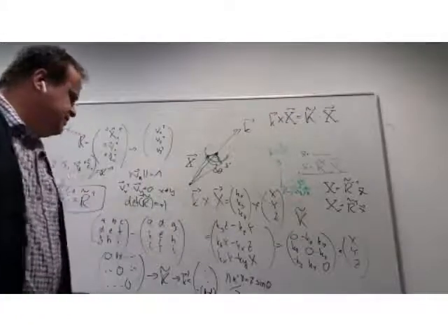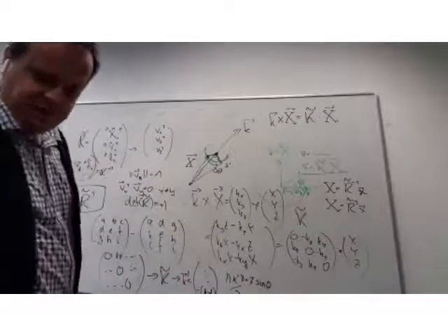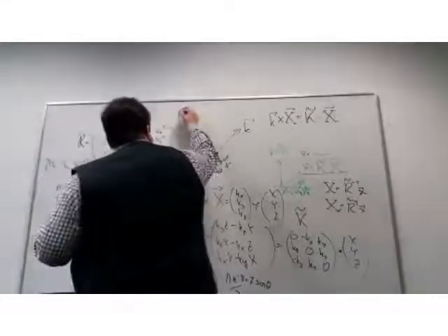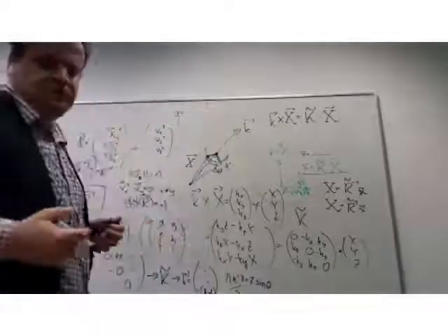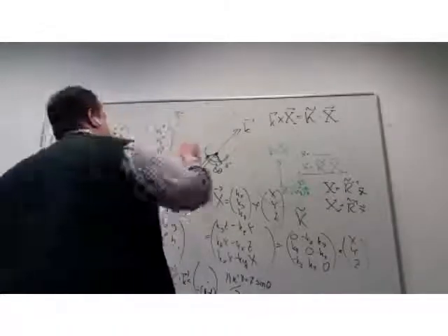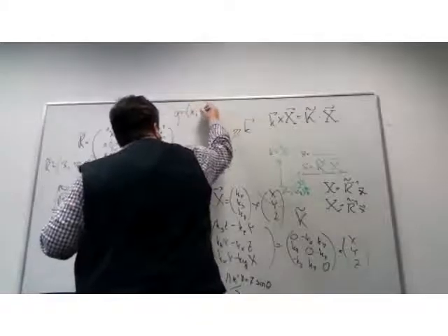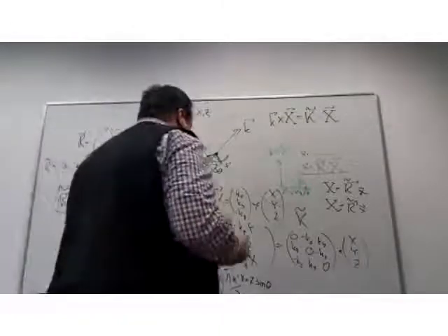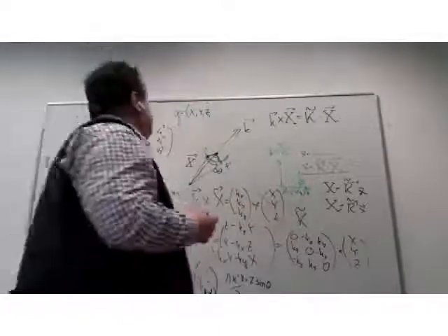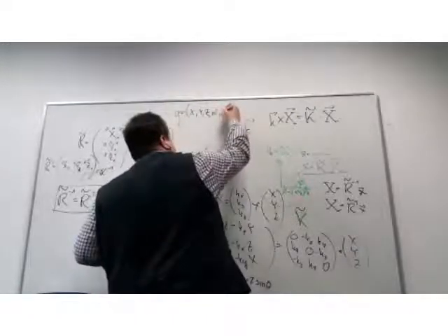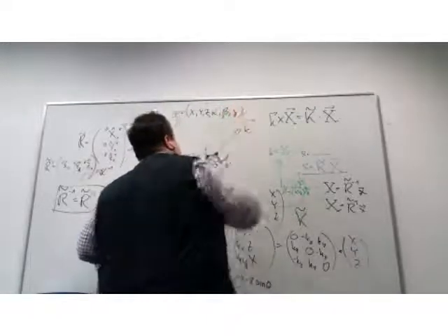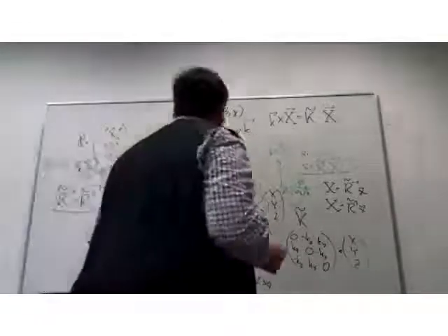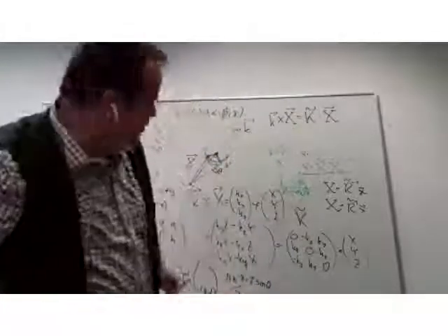So what's the configuration space of the robot now? Now we know basically the degrees of freedom. We know that we have 3 translations in our configuration of the robot. Our configuration of a point, an object in space, consists of its translation parameters, x, y, and z. And if we use the Euler representation, it could be a sequence of 3 Euler angles, alpha, beta, and gamma.